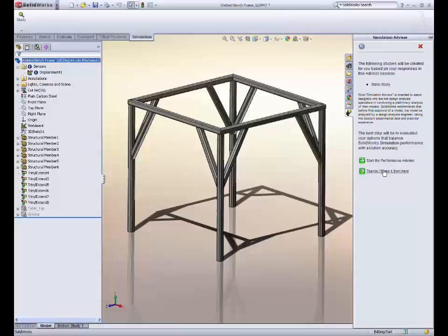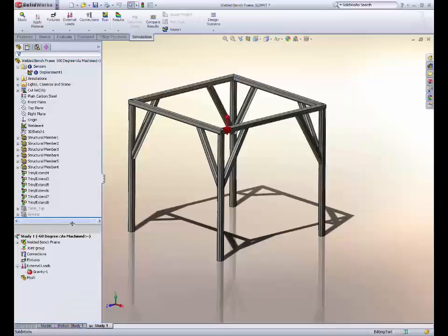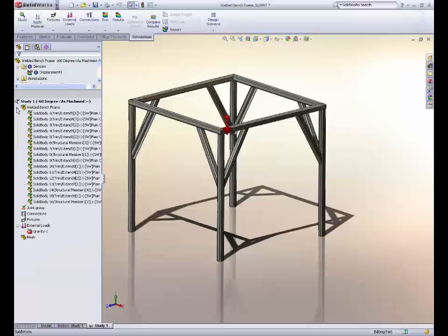There are several ways we can represent our design, and by default SOLIDWORKS Simulation provides the most efficient way. Our structure is made of weldments, which are long and slender. It will represent these as beams, automatically using the section properties of the geometry in the simulation. You're free to adjust the representation back to solids, but beams allow us to get insight into which design is better in a matter of seconds.